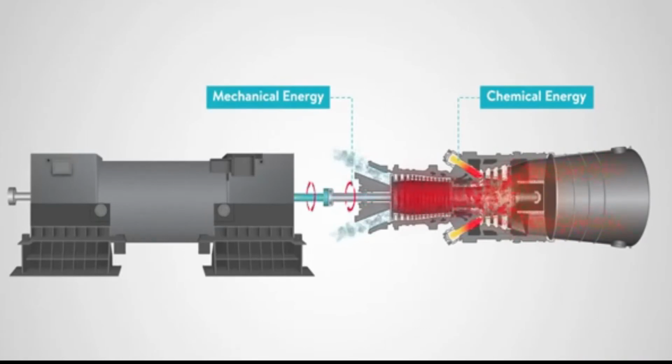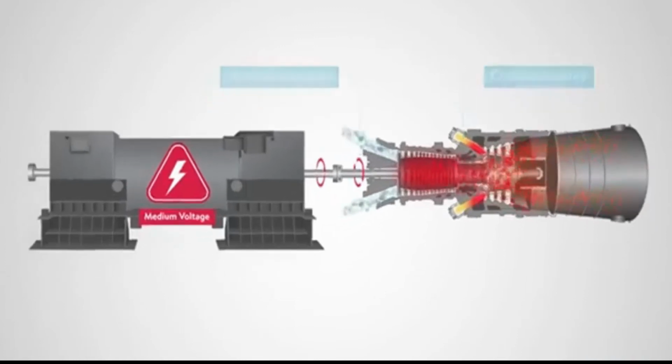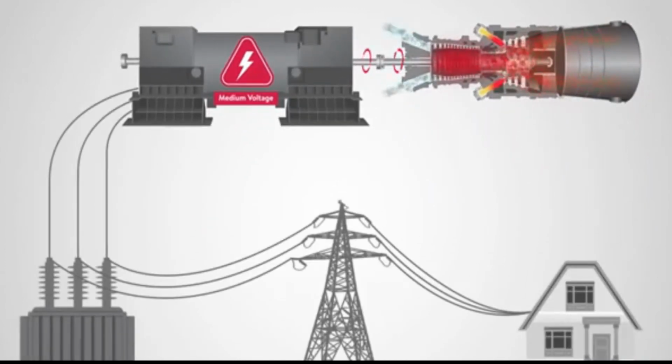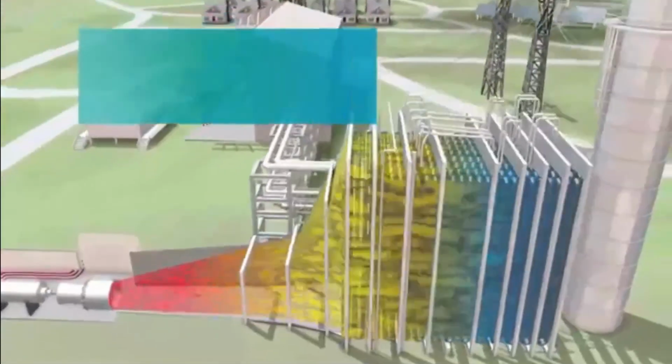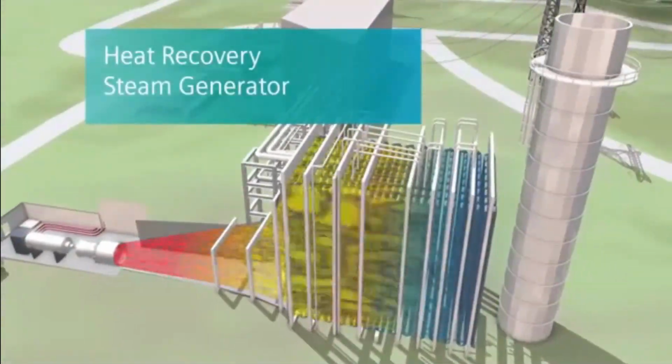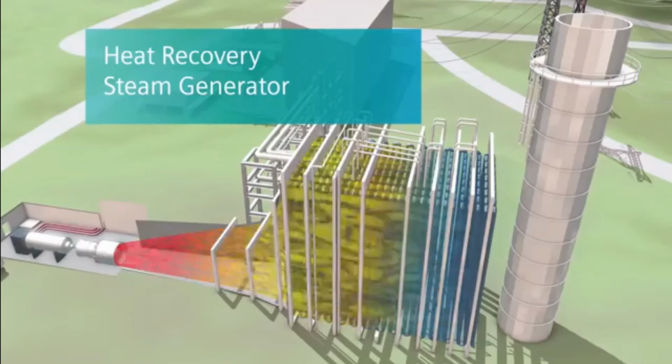The efficiency is usually less than 30%. The gas turbine plants are built with multiple units of 10 to 250 megawatts each, with a possibility of adding combined cycle thermal generation on every pair of turbine units by using the exhaust gas temperature reaching 540 degrees Celsius.